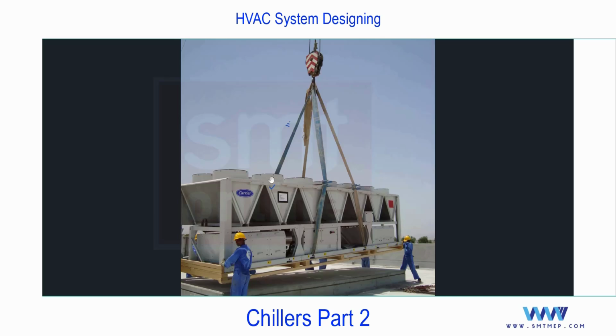So with this construction you can find, say, air cooled chiller, and we are placing it outside, because in water cooled chiller you'll not find the fans. In air cooled chiller only you'll find the fan, because the major difference between air cooled and water cooled is the condensing side only. Okay, we'll do the conclusion at the end. Let me proceed.